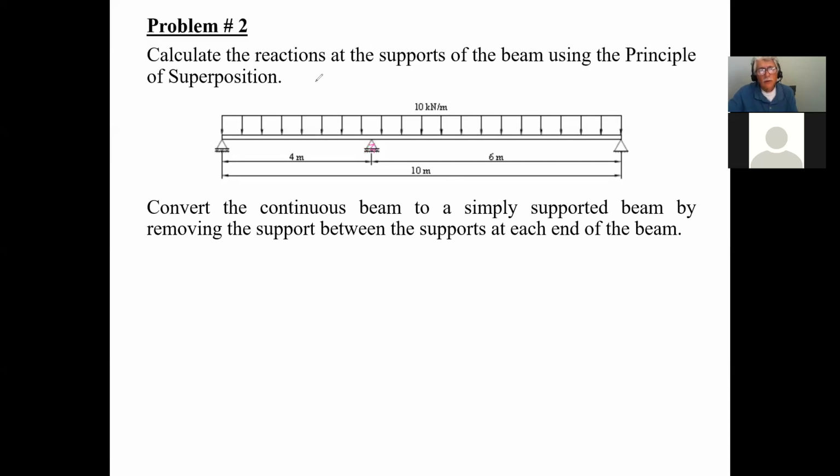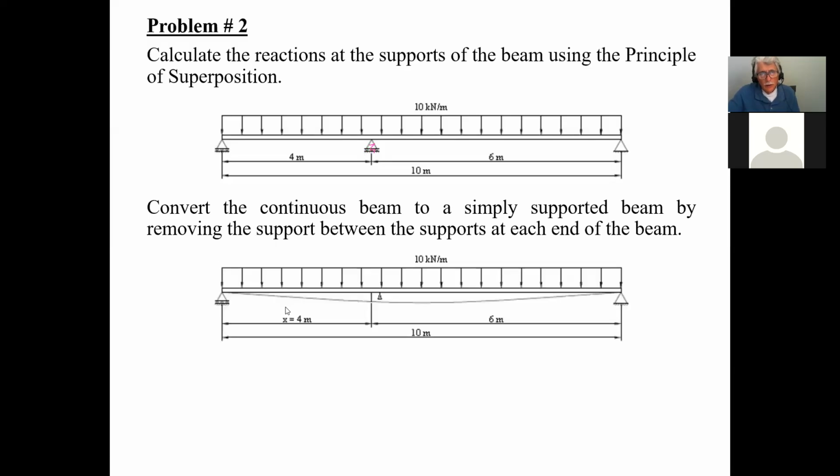And we're saying to ourselves, okay. And then we say, now, if I can calculate the deflection right at that point there, and of course this becomes X, and because I'm trying to calculate the deflection somewhere along the beam for a uniformly distributed load, and this, where I'm trying to calculate where the reaction was, 4 meters. Now, what you have to be careful about and keep in mind is that the span, the L, now becomes 10 meters, no longer 4 or 6 meters. So that's the only thing that you have to be careful about. And of course, this stays the same.